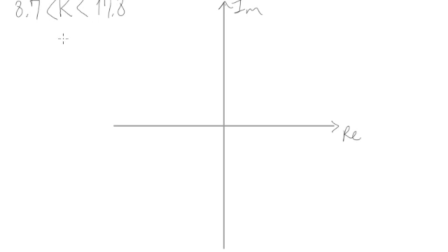So from here we can easily go to the other. So this is the design parameter. We can easily go to the system parameter, the natural frequency. We know that it is the square root of k. So here I can easily say that the natural frequency is between 2.9 and 4.2. Okay, so these are rough values, but I know that this omega n is between these values.